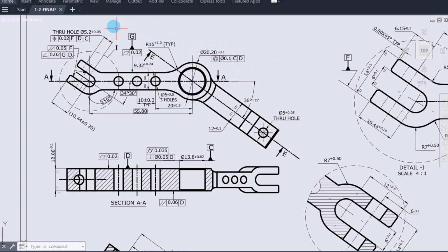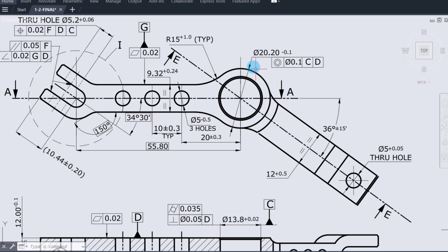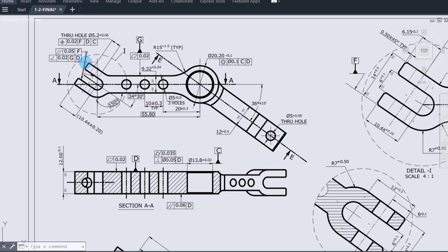So, let us analyze this front view. As soon as I see this front view, we see one circular boss with a center hole and 2 arms. The arms have forked ends. You can see we have a fork end here and another fork end here. And of course, there are several holes here. This center boss acts as a primary reference for many dimensions. The arm transfers loads and the fork end will probably connect to another pin or linkage. Instead of randomly dimensioning every feature, the designer organizes dimensions from important reference locations. That makes manufacturing much easier.